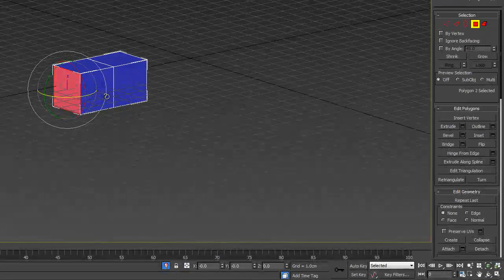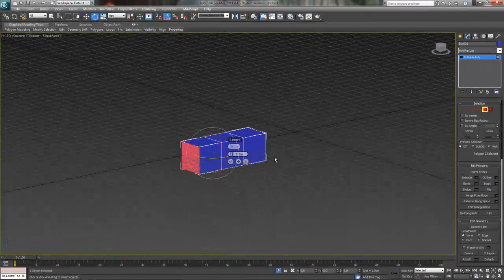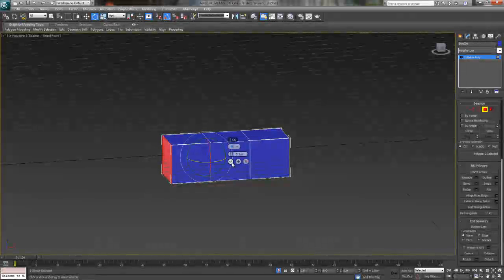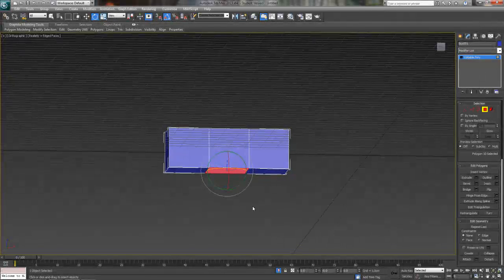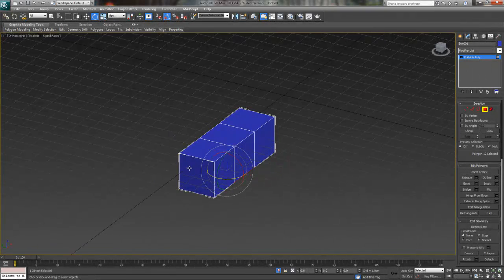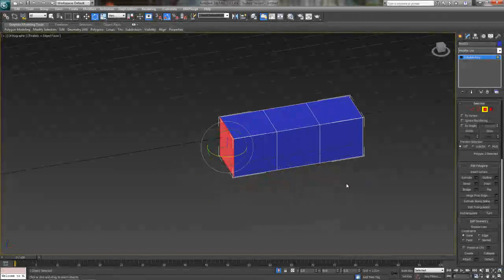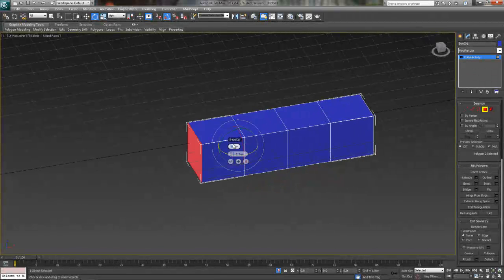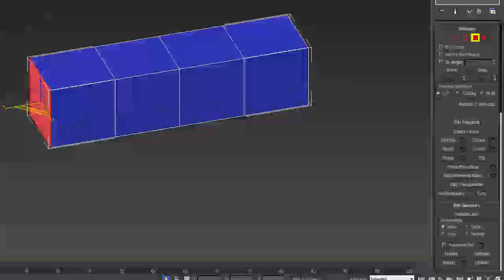And now what I want to do is extrude this one more time to 2.5, and this is where the handle is going to come down. But first of all, we want to create the end of the hammer, the hook, as you may know it. So if I extrude this, what I could do next is scale this face using scale. That's just next to rotate, or R on your keyboard.